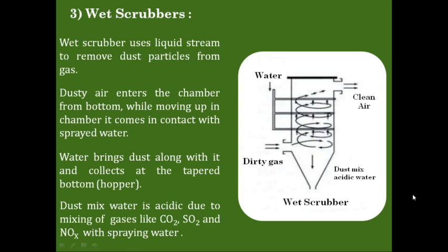So that dust mix water which is collected at the hopper or the bottom point is actually acidic in nature, and managing or treating this acidic wastewater is again a problem. Otherwise these wet scrubbers can perform very well in separation of dust particles from the industrial polluted gas.